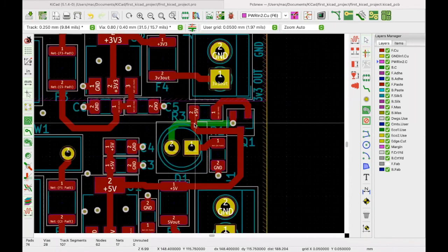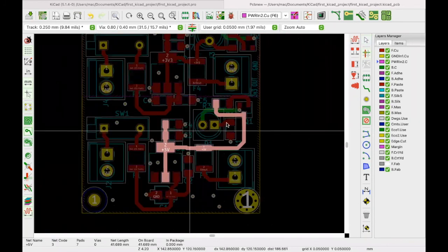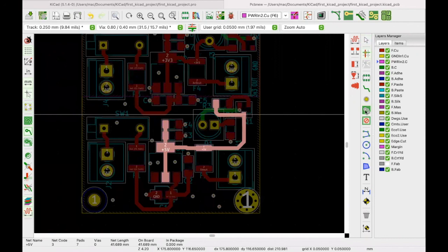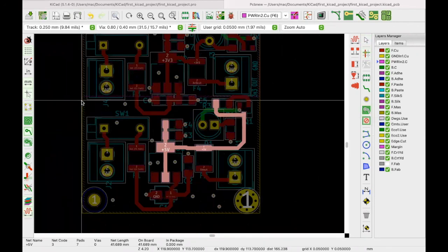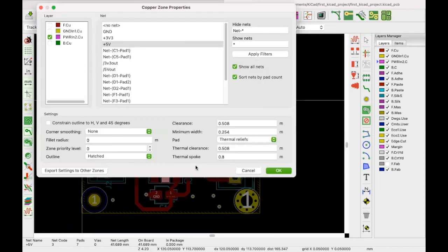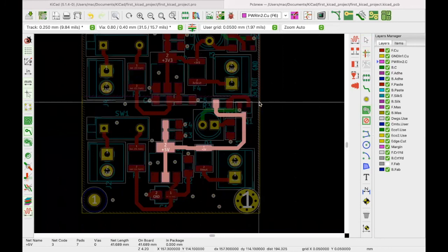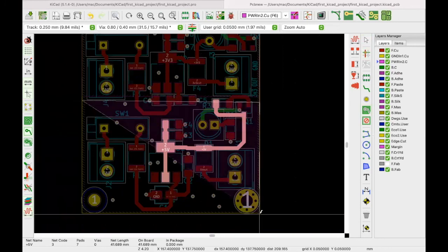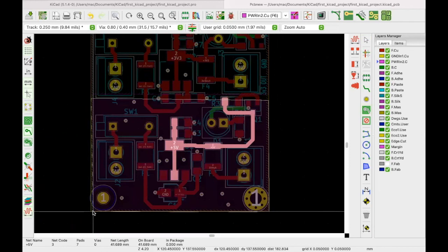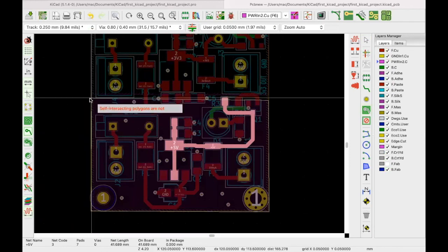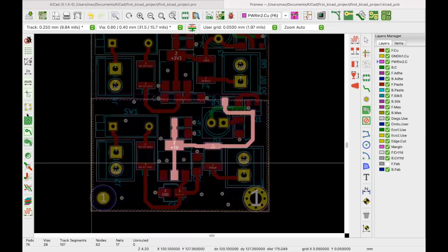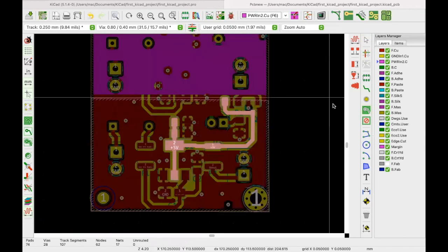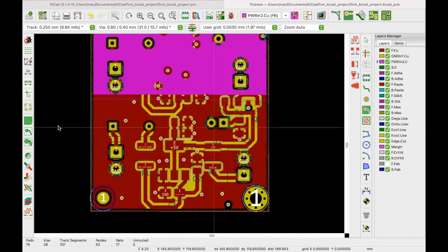So what I'm going to do again is take this tool again. So I'll select the 5V so that you can be a little faster. Then select on this one here, and then hit anywhere on the PCB. It's going to select 5V, then say okay here, then just throw it inside here. So I'll just highlight it here and hit here, and then come on here and close zone.